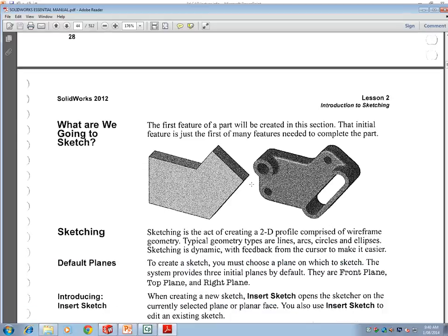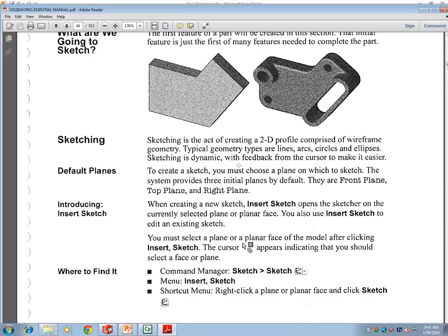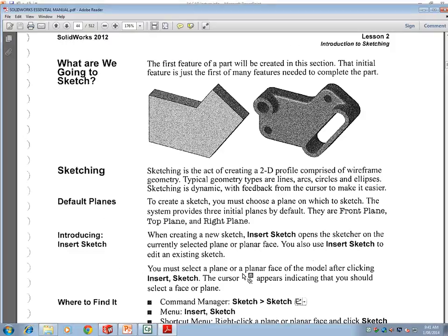See, most importantly, what profile you're going to draw is determined by the solid itself. Okay, it's very clear. This particular solid, whatever you're seeing, has a couple of holes, cuts, and some solid base as well. Okay, so depending on the type of the profile, we can start drawing your base sketch. So that determination is very important. But apart from determining the profile, you also have to determine which plane you're going to insert the sketch. Those are the key things. Determining the plane, determining the sketch profile for your part is the first thing that you have to do from your design intent. Okay, so once that is decided, then we can start drawing the sketch.